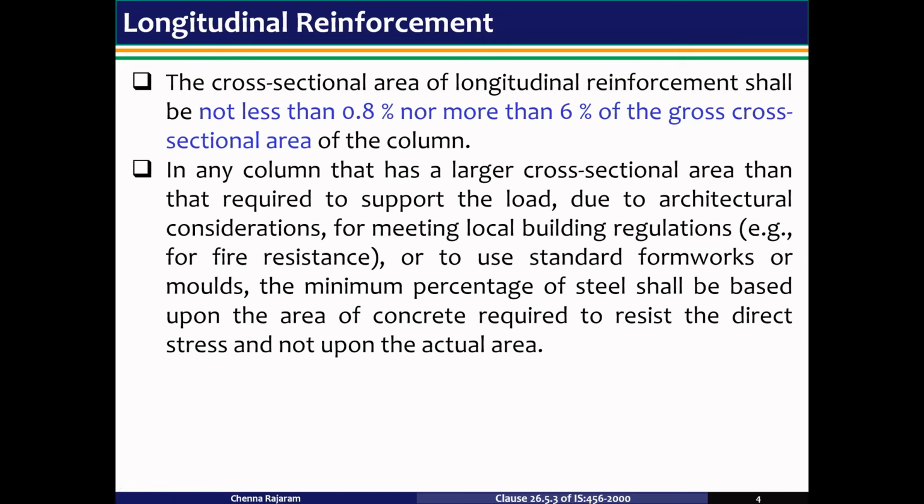The minimum reinforcement limit is to ensure the flexural resistance under unforeseen eccentricity in loading, and also to prevent yielding of bars due to the shrinkage and creep effects. The maximum reinforcement limit, in practice, is only 3 to 4%. However, a reduced maximum limit of 4% is recommended in general for better placement of concrete, particularly at spliced locations.